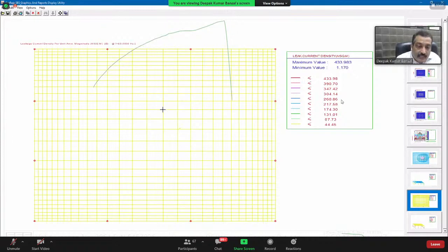So I did the designing, and I did various iterations and made use of a minimum number of conductors to make the grid safe. Then they told me that almost 50% of copper was saved, and that grid was more than, I think, half a kilometer big. So a huge amount of conductor they have saved. And apart from that, they were 100% satisfied that what they are doing is 100% correct.